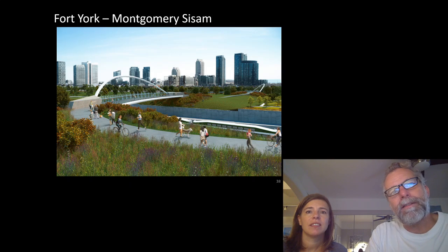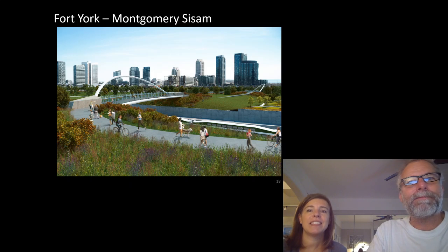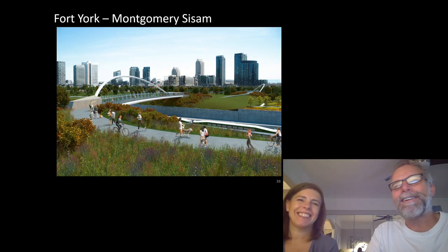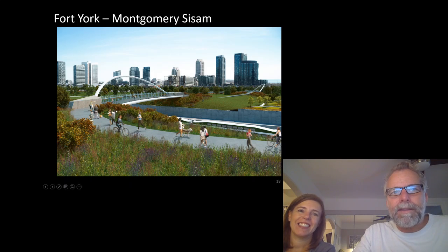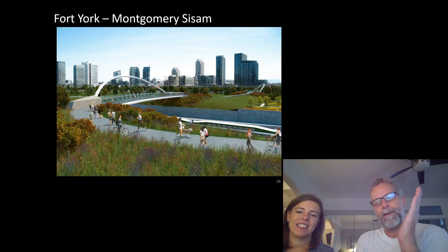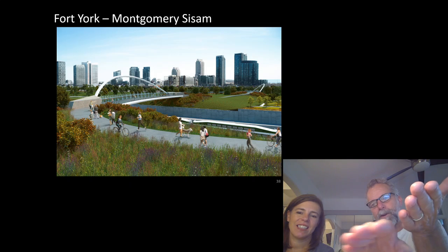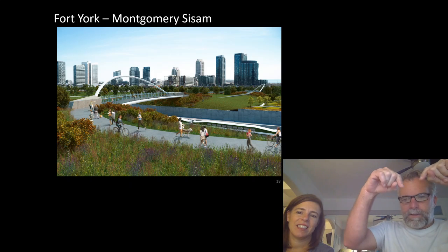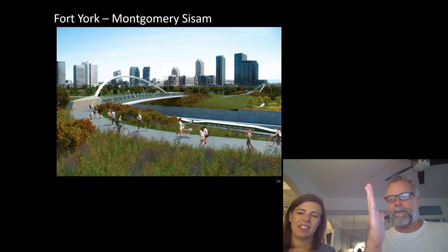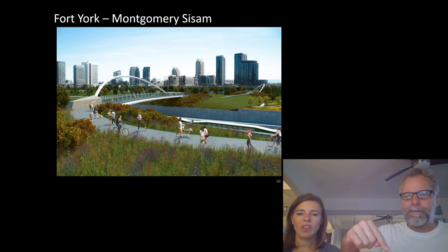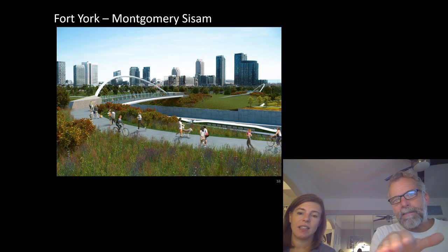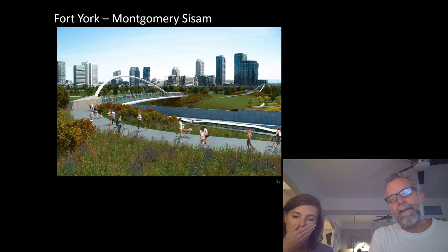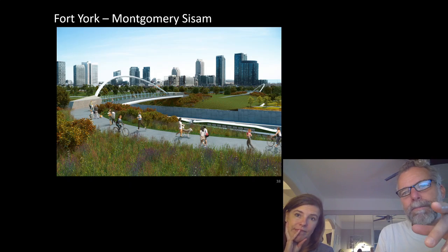So we move on. This is the one that we were involved with. This is the one that didn't win, the unsuccessful version. This one you cannot see quite, but this one is curved in plan as well as an arch. And if we consider the arch this way, the curve is under the arch, so that when you look down in plan, tip the arch off, it creates a curved crescent-shaped profile, the plan projection. In this case, the deck followed that.